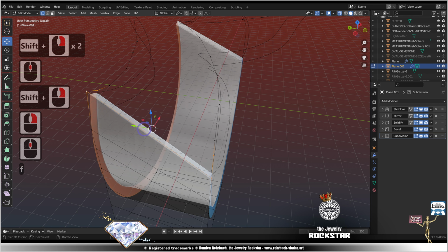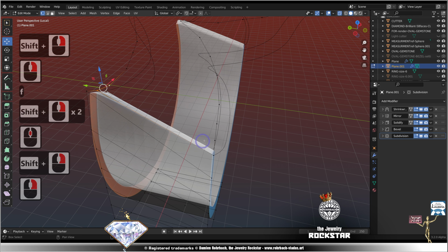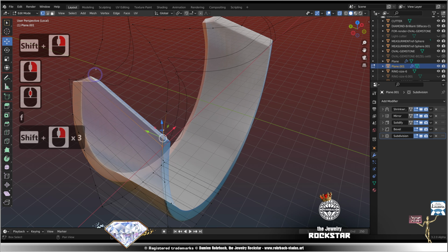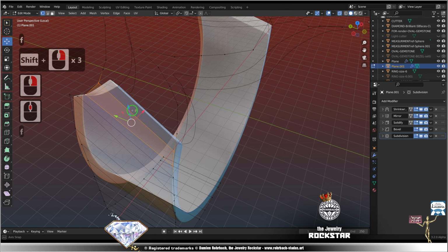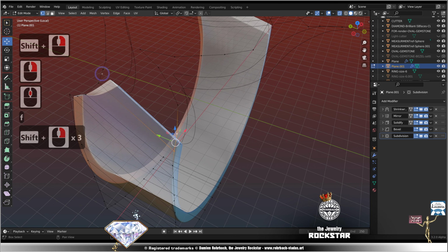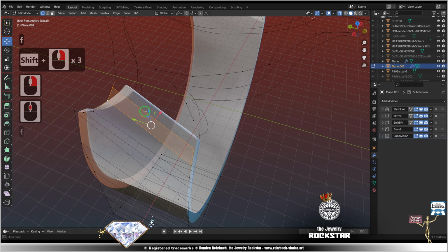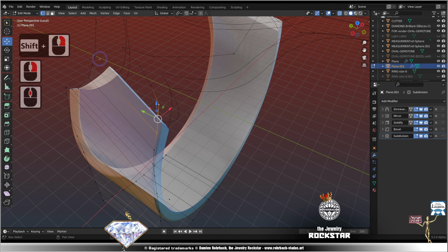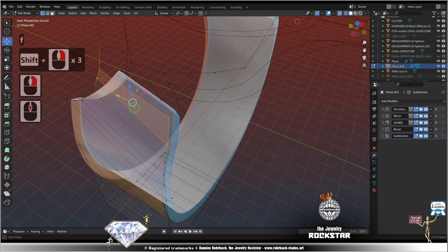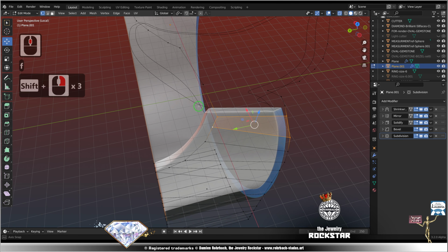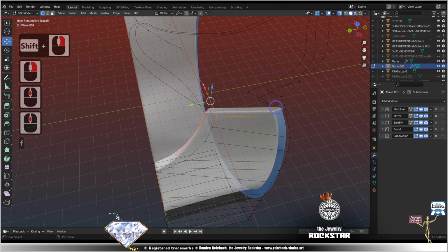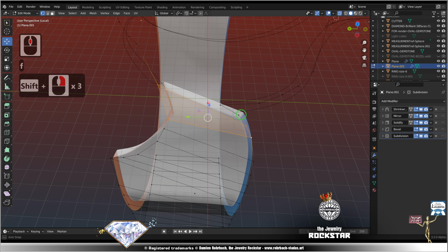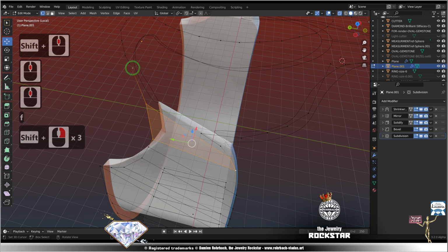Generally, we know that when we can't be sure that the vertex count is even on each side, well, the grid fill or all these kinds of functions or tools won't work, because the software won't find any solution or good solution, and this will be a problem.